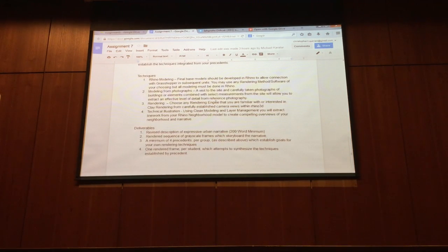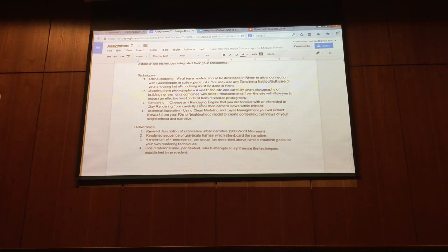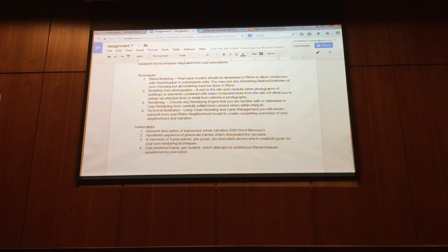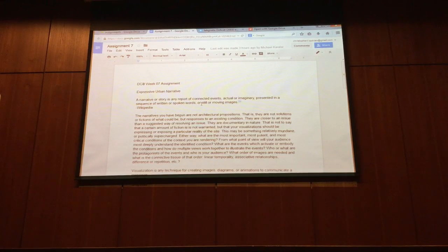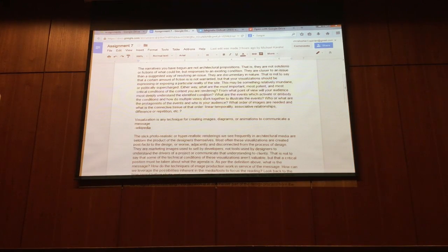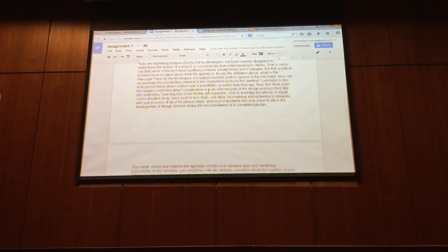And then you can use technical illustration. You can use Make 2D. There are really two kinds of ways to go about this. You can simply type Make 2D in the Rhino viewport, get some line work, clean that up, bring it into Illustrator, or you could use a non-photorealistic rendering engine such as Freestyle, right, which is going to do all of that sort of technical layering style, but also render it and give you the same level of control without the sort of mechanical means and the slow process of drawing. So there's a link at the end of the lecture that has some information about how you might go about doing that.